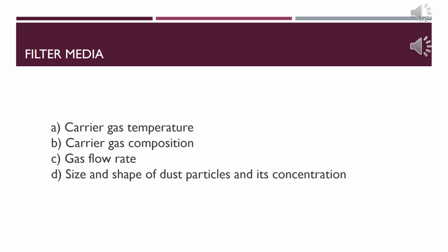Woven and felted materials are used to make bag filters. Woven filters are used with low energy cleaning methods such as shaking and reverse air. Felted fabrics are also used with low energy cleaning systems such as pulse jet cleaning.